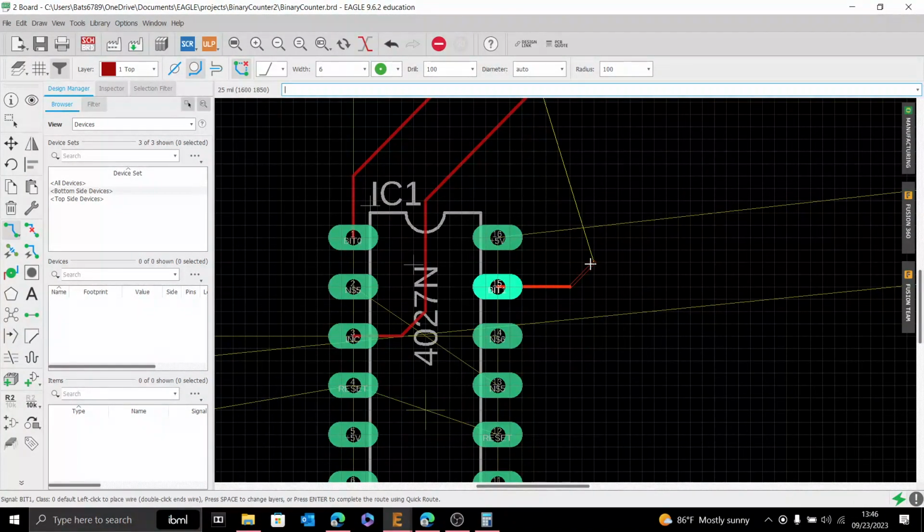So a good design rule you hear a lot is don't put 90-degree turns in your traces. I'm not going to argue whether or not that's a good rule or not. Some say it's archaic and doesn't need to be considered anymore. My boss doesn't like it, so I don't do it. Part of it is that it becomes a sharp point, and that can cause some signal issues. And I think I even read something about some sparking in high amperage situations. And so just don't do it. Try and keep it 45.